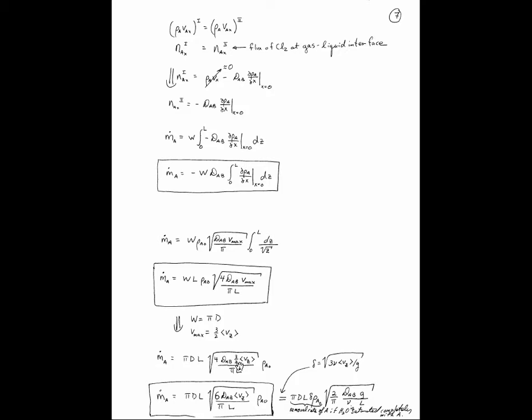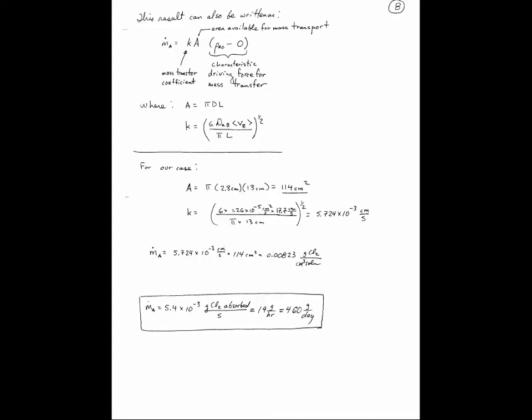Essentially what it comes down to is that the rate of absorption of chlorine is equal to a term which is essentially the rate of absorption if the water were completely saturated with chlorine, times a term that gives you what amounts to the fractional saturation, and that term depends upon the diffusion coefficient. Essentially it depends on how much contact time the gas has with the fluid.